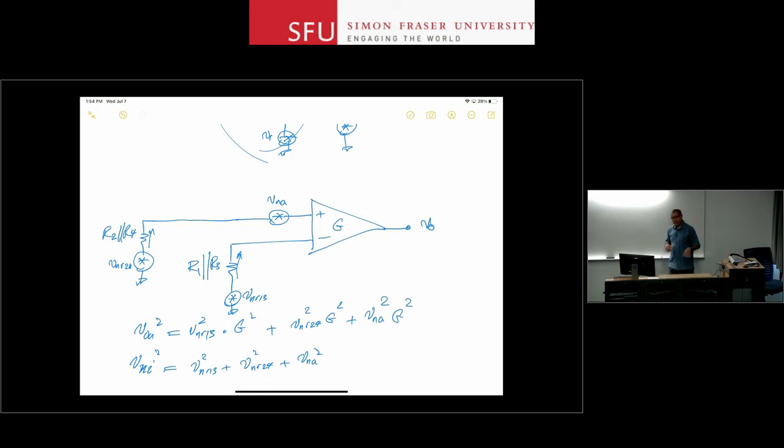Now, remember, these numbers are power spectral densities. At the end of the story, it is voltage squared per hertz. So you need the bandwidth information. You need to know how much the bandwidth of your system is in order to calculate that as a voltage squared number. In this case, I think it was told that the bandwidth is limited to the resonant frequency of the structure. So once you have the K and the M, you can calculate the bandwidth and multiply this number V squared per hertz by that bandwidth, and you get a V squared value for the variance of your signal.